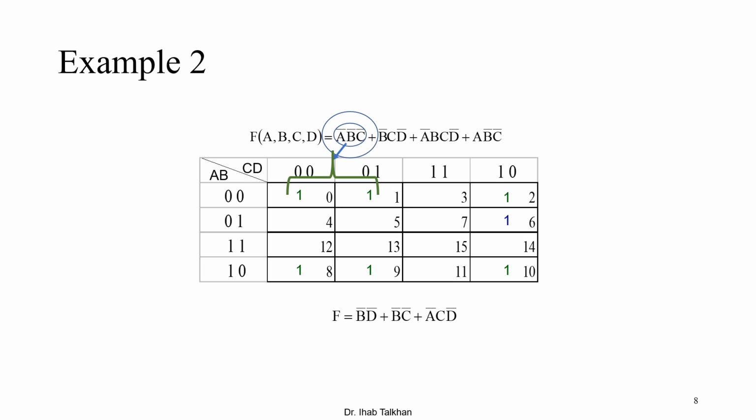So now we need to find the position of the ones in the truth table or inside the KMAP. First of all, we have to go term by term. The first term here is A bar, B bar, C bar. We need to find where the ones representing A bar, B bar, C bar are. So the first thing we do is find where A bar, B bar is. A bar, B bar means the row which contains A equals 0 and B equals 0. So the first row is representing A bar, B bar, where A equals 0 and B equals 0. Okay, and now where's C bar?